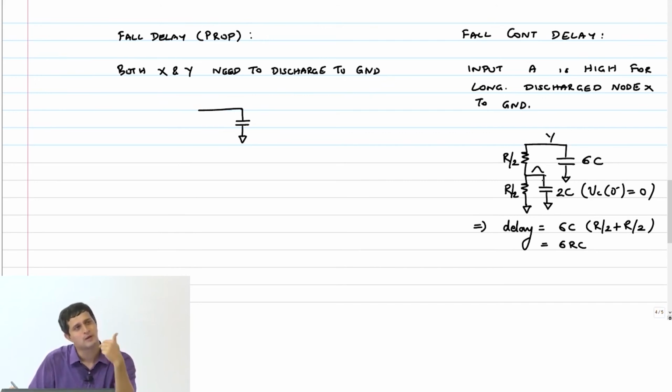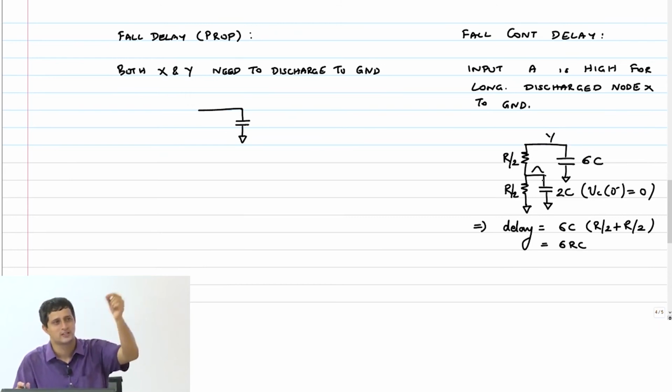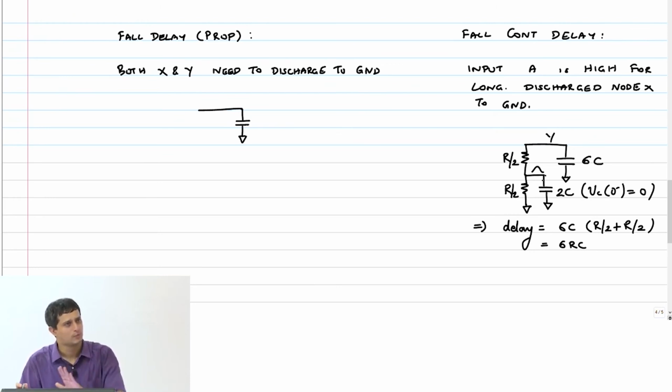But that becomes a second order effect, right? So in the Elmore delay approximations we made, we said that everything falls as VDD e power minus t by RC, right? Those are only approximations. You can go check it out in simulation for yourself, but to a first order, this is a reasonable approximation to make, okay?